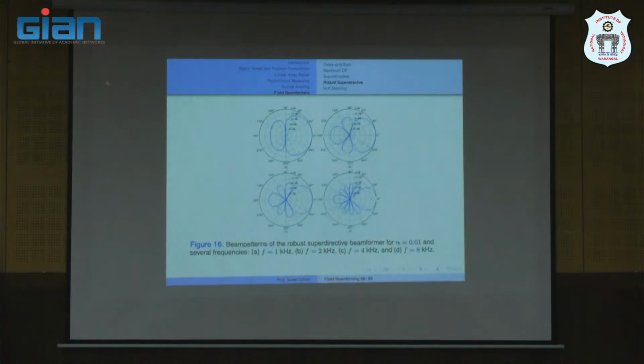If it decreases, the directivity factor decreases, so the beam becomes wider. Because if we have a wide main beam, what is the directivity factor? It's actually the ratio between the value in this direction, which is always 1, 0 dB, and the integral over all directions. So if the main beam becomes wide, it means that we have lower directivity.